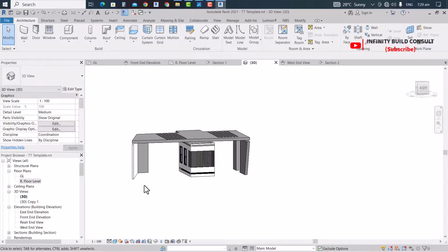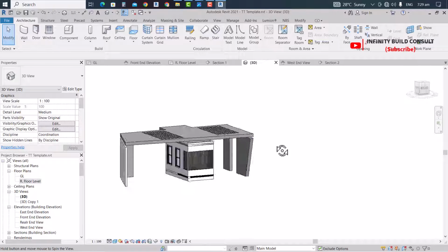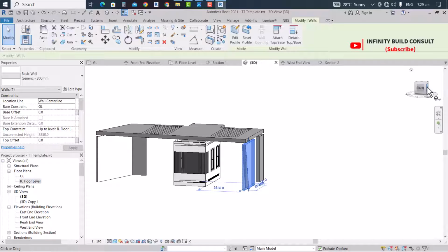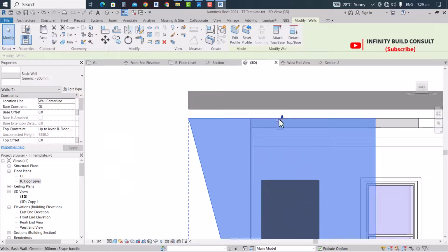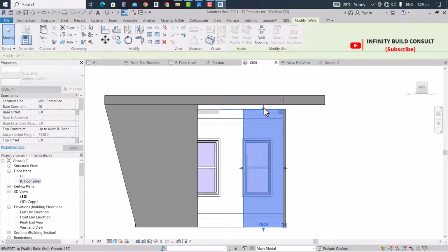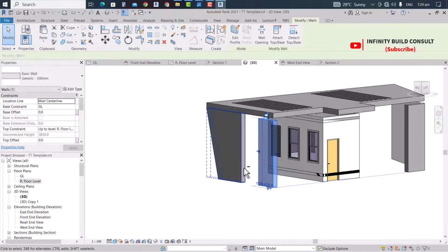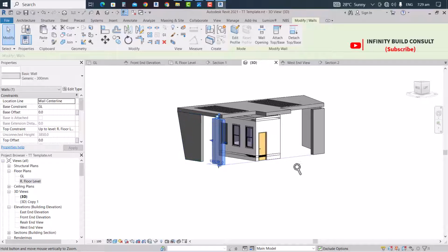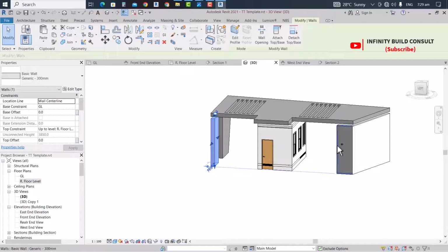So back into our 3D, we can see our drawing is coming into view. So I'm going to extend this one to hit the edge of the roof and also do same for this, or better still, because this hasn't been reset or the profile has not been edited, I can select these various walls and increase the height, which might be 200 mm or 150 rather.